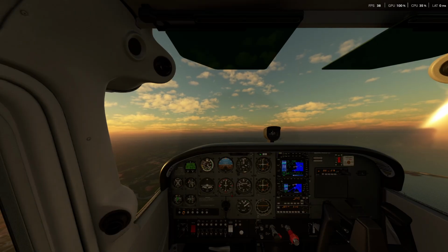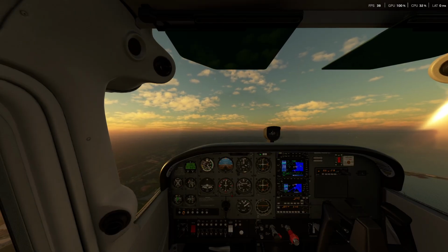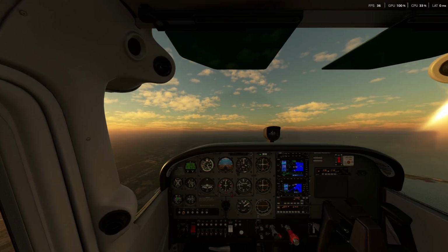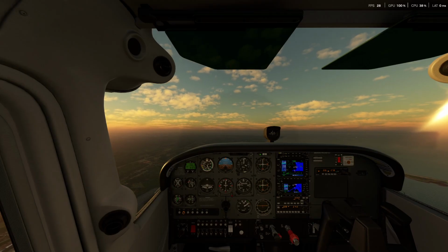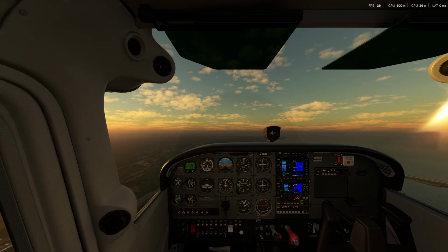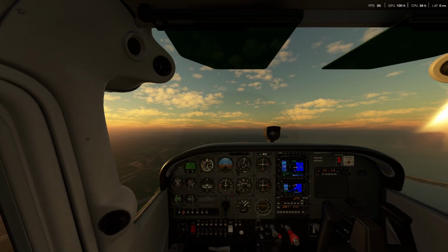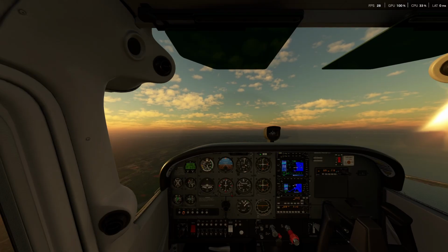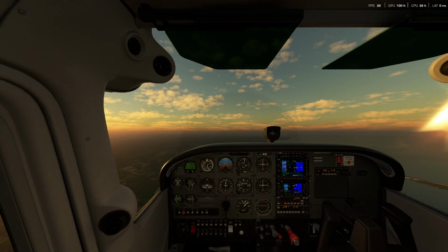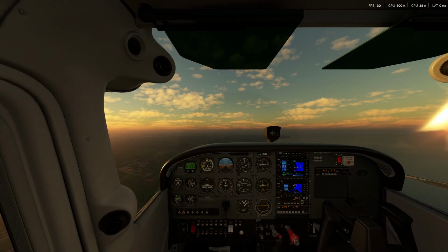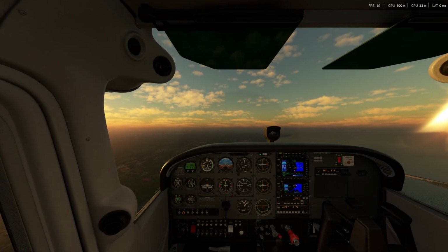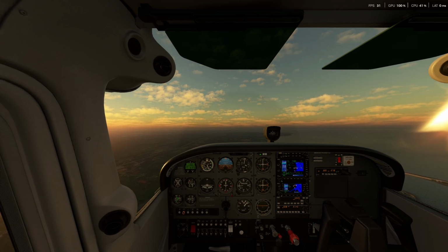Slow flight is also a lesson that we're going to go over. But one thing you can see too is when your airspeed is low, you have a higher angle of attack on your plane. I'll pull back the throttle here. When you're going slow, the relative angle of the airplane is typically a lot higher. So again, you'll see a lot less ground in the sky. It will almost indicate a climb because you see a lot less ground. But that's not the lesson.